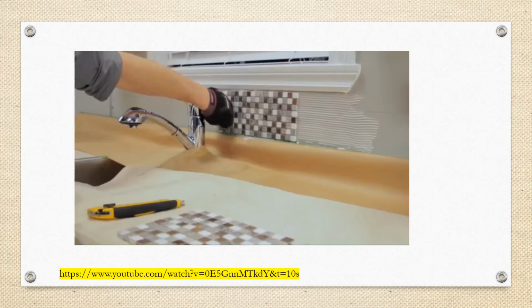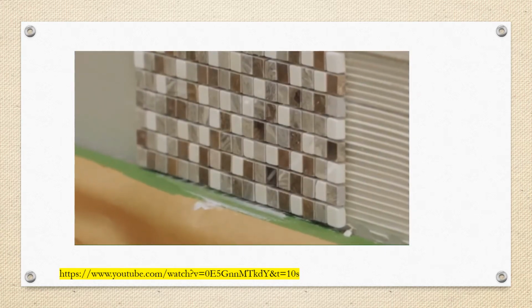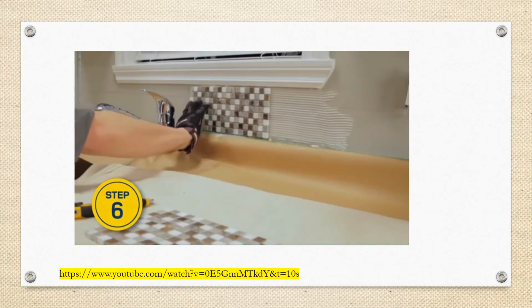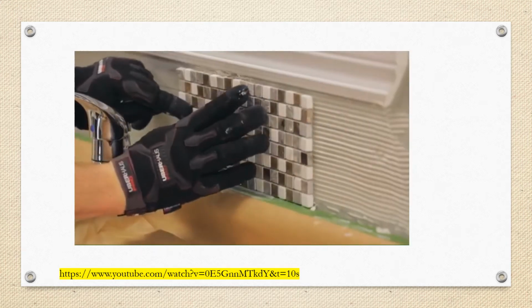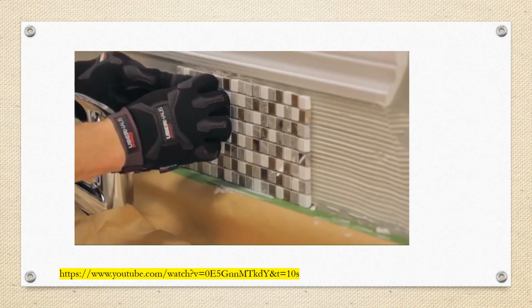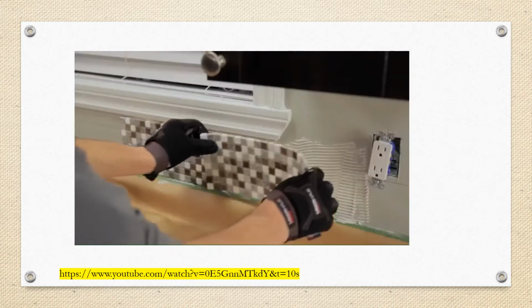Place tile spacers along the countertop so the tiles don't rest directly on it. Later, silicone will seal the gap between the two materials. Gently push the sheet into the adhesive to make sure it adheres well to the wall. If the adhesive squeezes up through the joints, remove the tile sheet, spread out the adhesive, and start again. Lightly tap the tiles with a rubber mallet to make sure the sheets are firmly set on the wall.